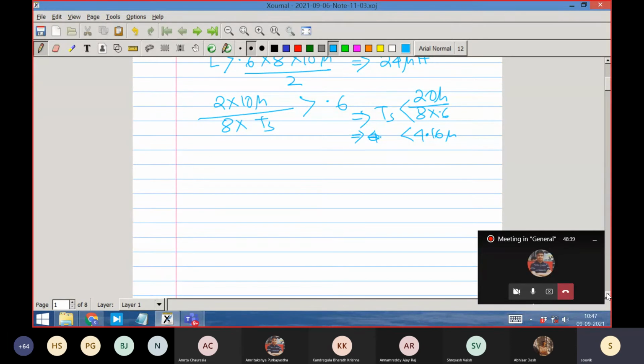Let us see if I can sketch the capacitor current waveform in the discontinuous conduction mode. So let's say this was the waveform. This was the current, and it was coming down to 0 here, and it remained 0 here, right? So this is the delta IL, which now we know, because we know D2. We can find out.